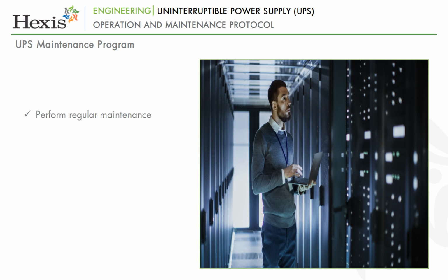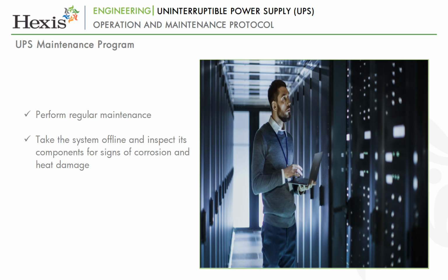The technicians should take the system offline at least annually and inspect its components for signs of corrosion and heat damage. A thermal imaging system can be used to identify loose connections and components that can overheat.